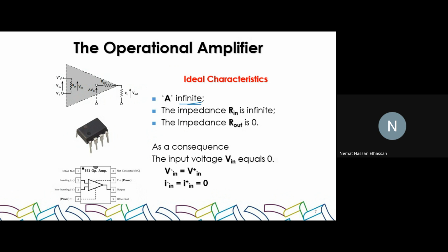Okay? Another thing is, please keep that in mind when you're working on your group project. Because if you use an amplifier, you're going to test it in simulation, which will be ideal, and you'll be testing it in hardware, and hardware is not ideal. So you might expect some non-idealities in the output, okay? The other thing we assume is that the input between the two terminals, between V1 and V2, is extremely high, that there is no connection between them. They are floating, as if this is an open circuit. Rin is infinite. The third assumption is R out is 0.